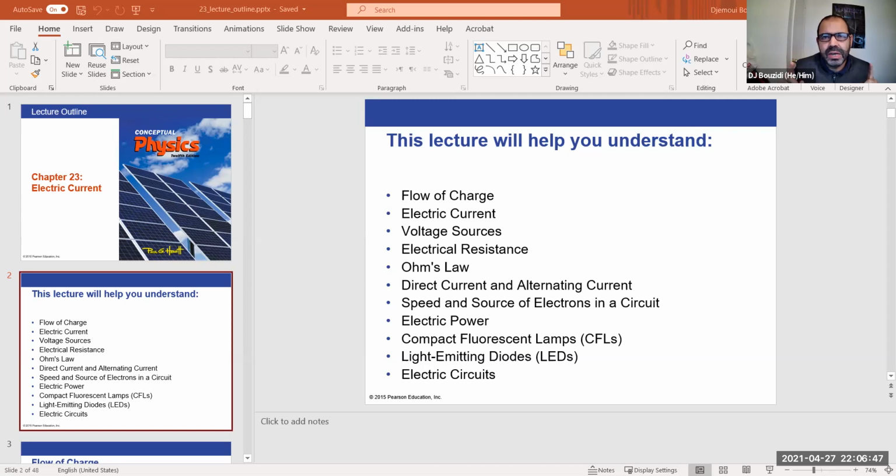So let's say, for example, you go and buy a 60-watt light bulb, and that will consume 60 joules in every second. So if you let it run for a minute, that's 60 times 60, that's 3,600 joules. And so on and so forth. The longer you run it, the more energy it's going to consume. At the end of the day, the power company will tally that number and add it up until you use this much energy. Therefore, we're going to bill you for this much.